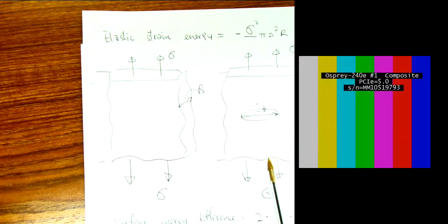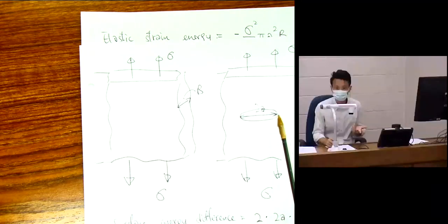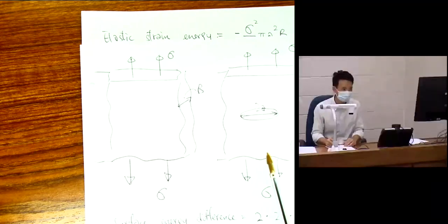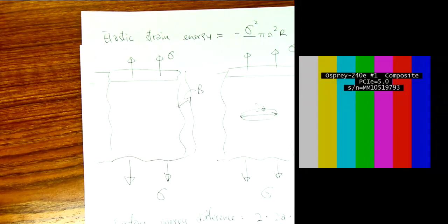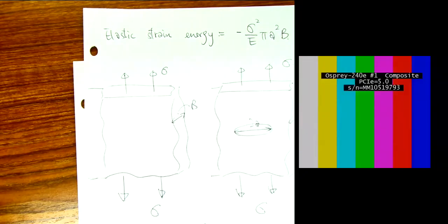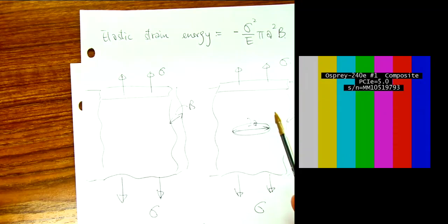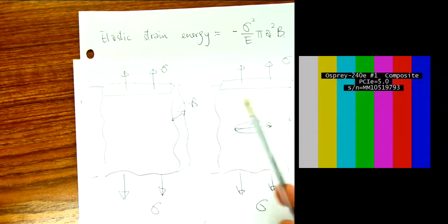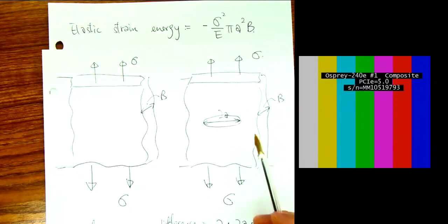This one is difficult, because to integrate, we need to know the stress distribution. We need to integrate the stress field all around the piece of solid, right? So what Griffith did is that he used the solution by Inglis. Inglis calculated the stress field for an elliptical hole, right? You're going to see that in your homework. What does the stress field look like?